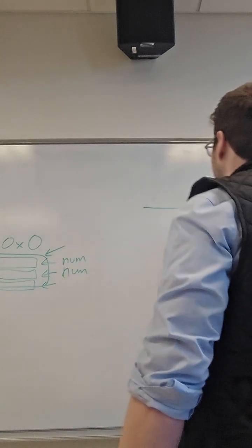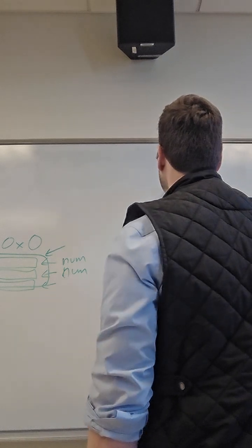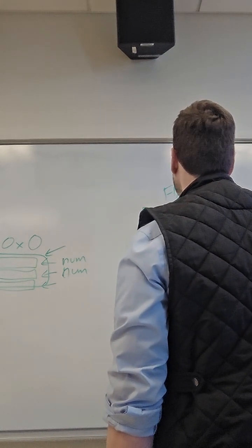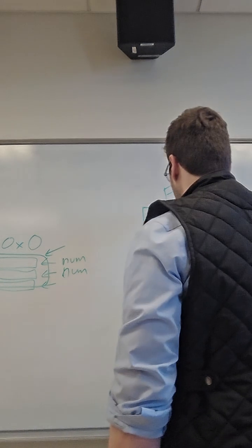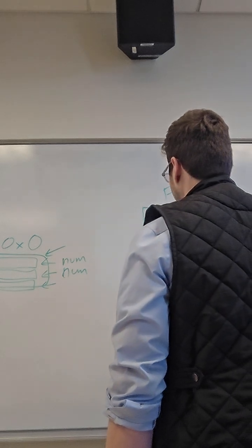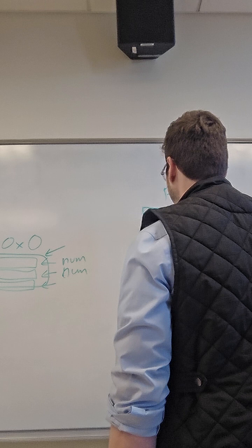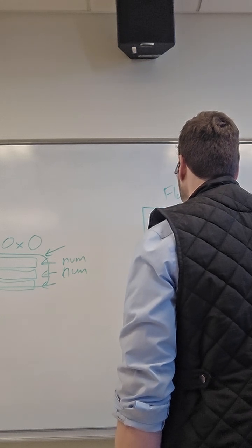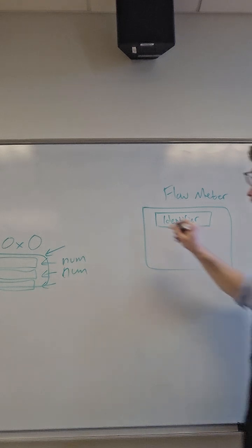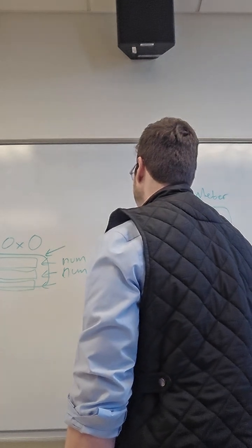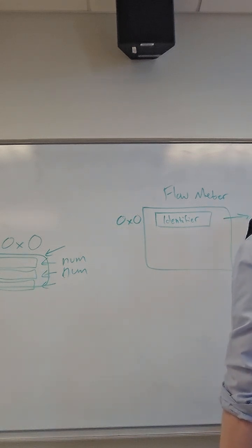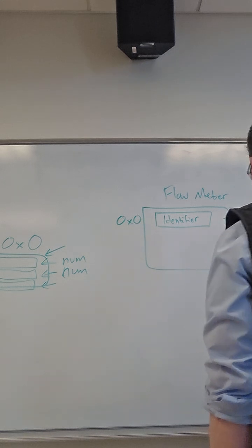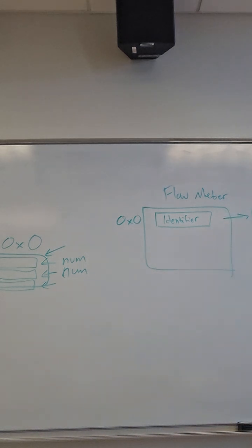Imagine if we had a flow rate sensor, a flow meter that was on Modbus, that talked Modbus. That flow meter might have an identifier, which is very common, a number that we expect. So if I read this register, it's called a register, if I read register 0x0 and I get back 0xAF, I don't remember what decimal number, but that's a specific number out of 255. One specific combination that is possible out of all combinations.